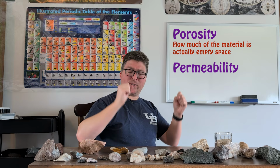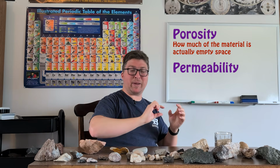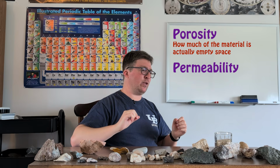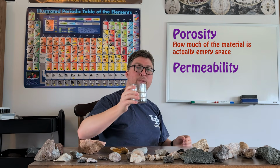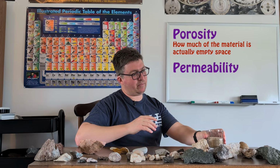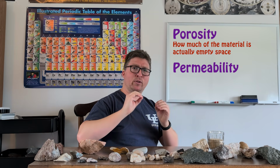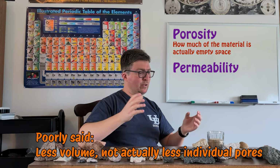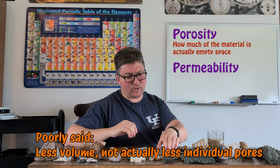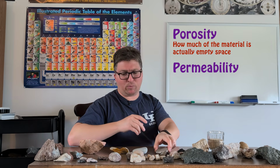Now, if you take fist-sized cobbles and put it together, you're going to have much smaller pore spaces in between. And if you take sand, I've got a little glass of sand here, the pore spaces will be even smaller because those grains can pack together. So it's not just a matter of the pore spaces being smaller, but there tends to be less of them also. And once you get down to a consolidated sandstone, well, now you've got very little pore space.